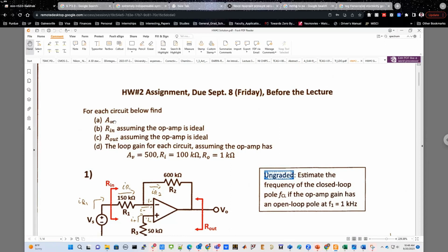This is something you have learned when you were studying frequency response as well, right? Because of the feedback, the gain of the system reduces by T0 times. In fact, if you do the math, it will reduce by 1 plus T0 times. So again, just going a little bit into theory. Remember the formula for negative feedback? It's A divided by 1 plus A beta, where A is your open loop feed-forward gain, basically the gain of your op amp. Beta is the feedback path gain. And you know that A times beta is basically the overall loop gain, which is T0.